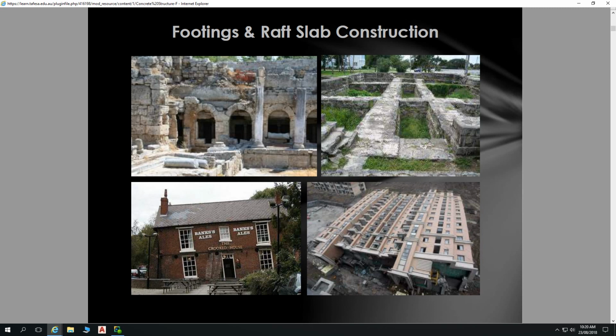One of the things that happens with steel in a slab, and steel in general, is that whenever it rusts, it expands. Oxygen joins onto those steel molecules and creates a lattice work on a larger molecule that needs more space, and it expands. When steel expands inside concrete, it cracks the concrete. When you get cracks, you get more moisture, more rust, more expansion, and so on. So we don't want any of that rust and expansion in the first place. That's called concrete cancer, and you see it happen around the place with some older buildings.